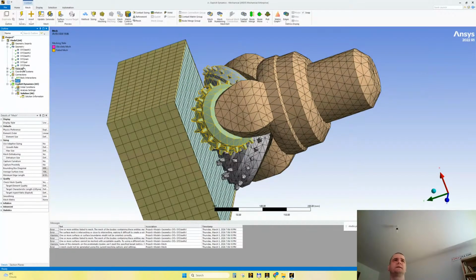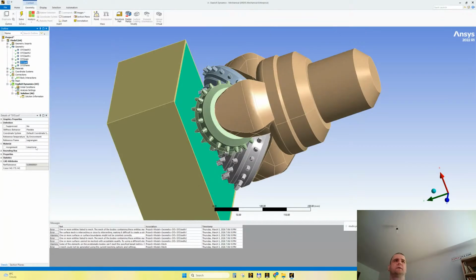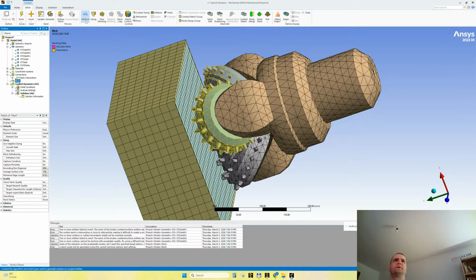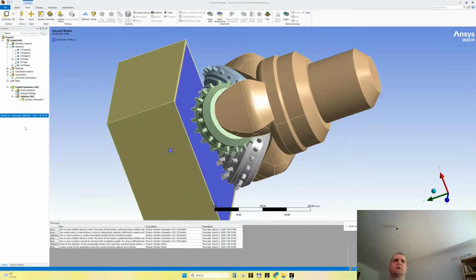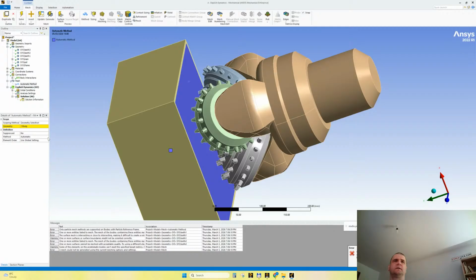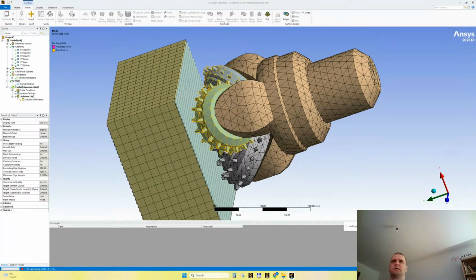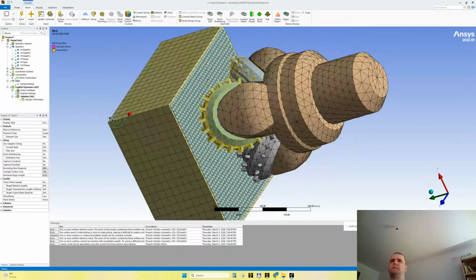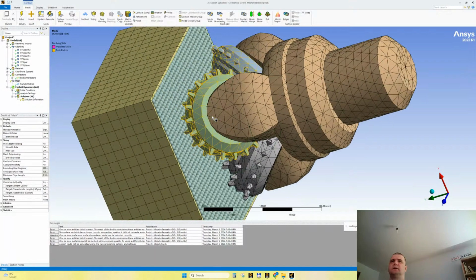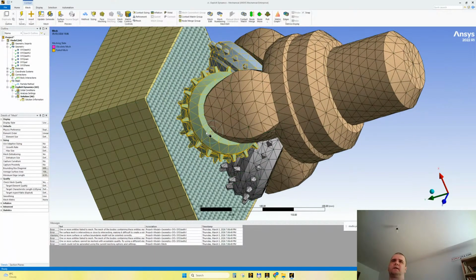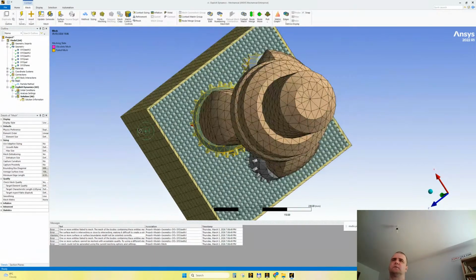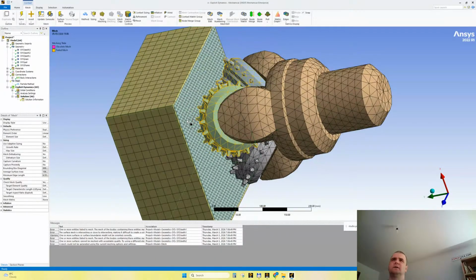And let's see if it will mesh as particle body. So here we need to go for method, click the soil part, and choose particle here. Let's leave default, generate mesh. Yes, it's getting meshed. This is the only way to properly erode, to drill and bore soil. I'm talking about using SPH body, particle bodies, yes.